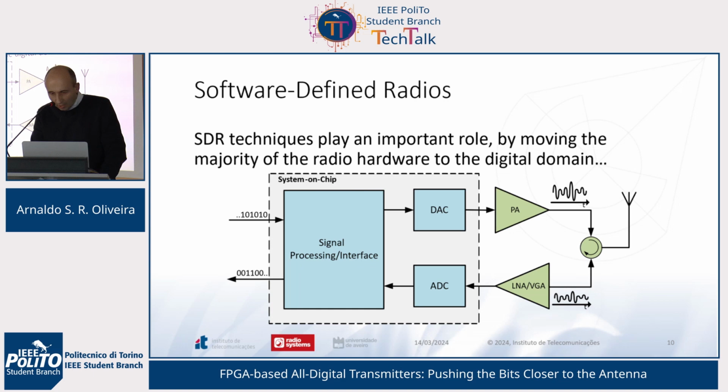Ten years ago, we started thinking, because our background, me and my students at that time, was mainly on the digital side. We used FPGAs very extensively for different purposes. At that time, FPGAs started to have available what we call multi-gigabit transceivers. They are basically transceivers that provide the support for the implementation of high-speed serial links. And we thought, what if we apply pulsed modulators, namely delta sigma or PWM, to the design of radio